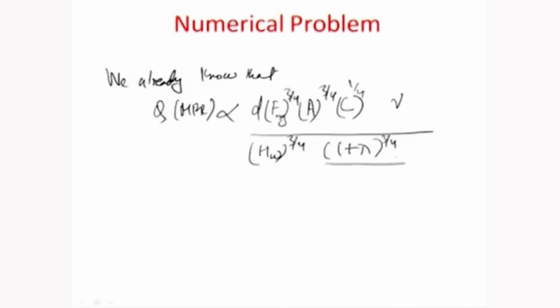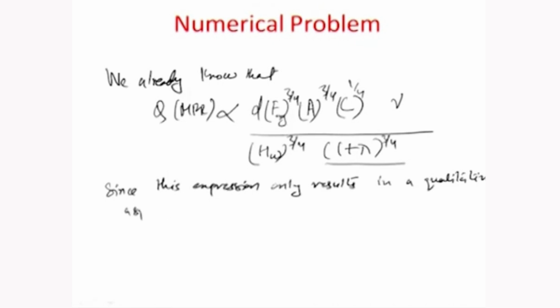Okay. So since this expression only results in a qualitative aspect of the machining process, for the sake of simplicity we assume that the volume removal per grain indentation can be approximated by a hemispherical volume.